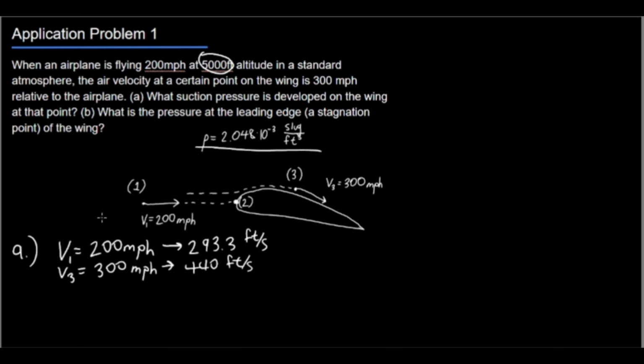So, with that, we are now, again, using the Bernoulli equation, which will take us from, in this case, point 1 to point 3. And that does follow a streamline. We can easily get there. This does not violate any of the rules or assumptions that the Bernoulli equation makes. And so this is totally viable.